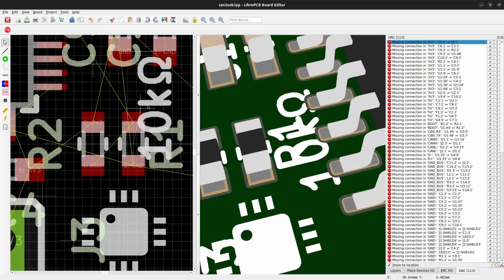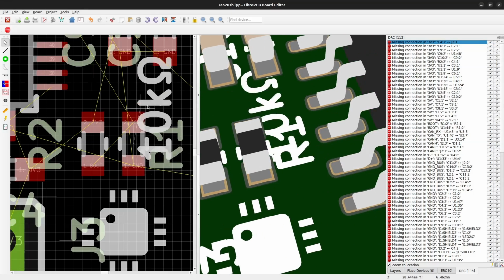By the way, you might remember that adding a device to the board copies the corresponding library elements from your workspace into the project, so any further modification in the workspace won't propagate into the project. If you modify, for example, a package already added to the project, you need to manually trigger an update in the project to receive these modifications.